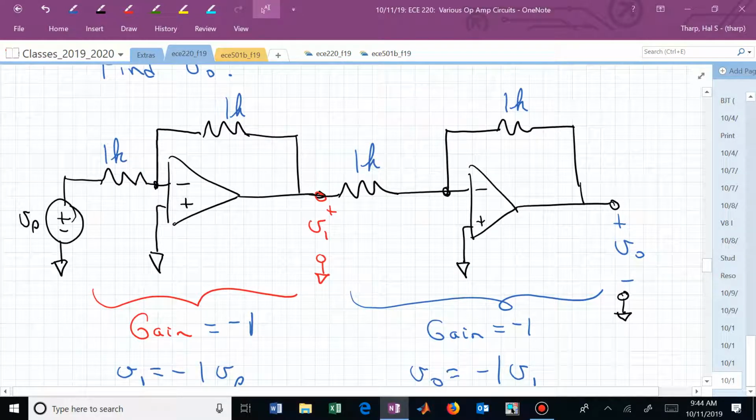Which, if you didn't want to invert your gain using an inverting, but you wanted to scale it, do you see you could cascade a couple of these together? You still have to worry about saturation, but now you can start interconnecting these, and that's how you could actually change these difference amplifiers into a better performing circuit like an instrumentation amplifier, which you can get to later after the final.